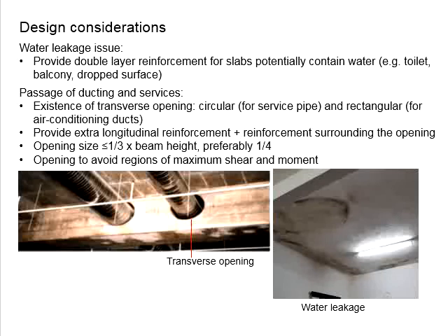Again, you require additional reinforcement bar, and there will be reinforcement bar surrounding the opening. Especially when you deal with square and rectangular openings, extra care will be required at the corners of the openings.